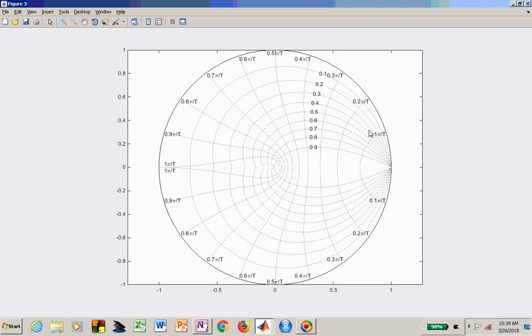If you now multiplied this omega sub n times T, you would now have 1/10 pi, or 18 degrees, 36 degrees, and you could draw these angles, and those would be your angles corresponding to peak time. But these curves that are perpendicular to the logarithmic spirals, which are the zeta curves, are actually our natural frequency curves corresponding to a particular natural frequency, and they've now been labeled on the unit circle, but those now migrate through as we increase the value of zeta.